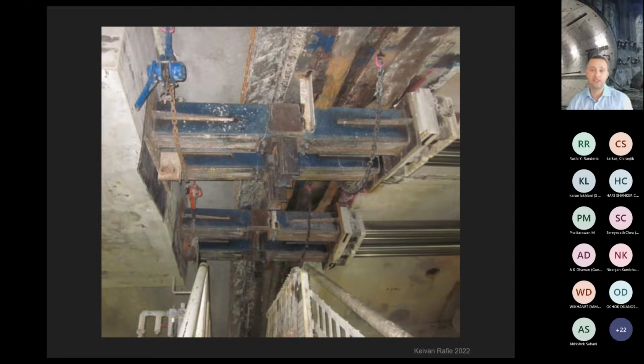Next, extension struts were installed to fill the space between the truss block and the truss cylinder pads. In this manner, the forces were shifted to the truss block and then to the rock through the tension in those bolts.